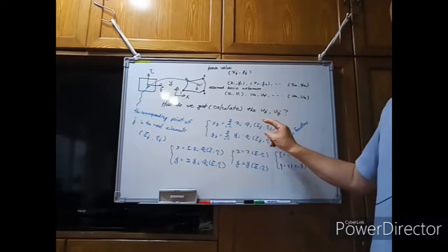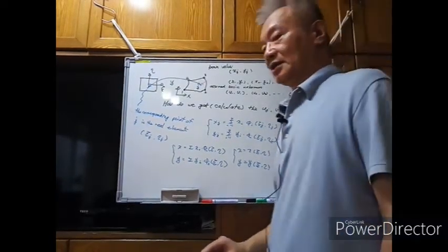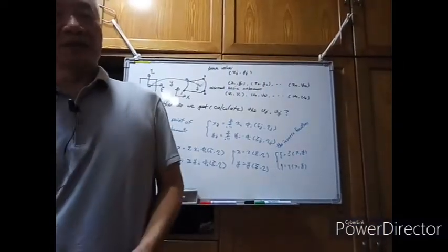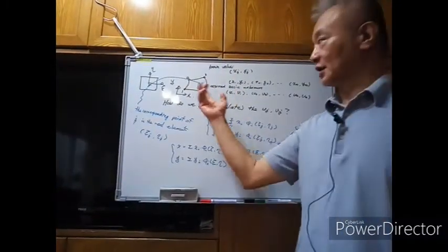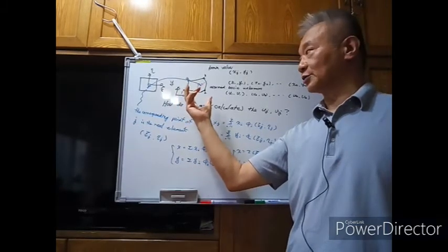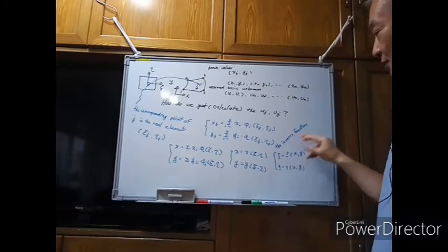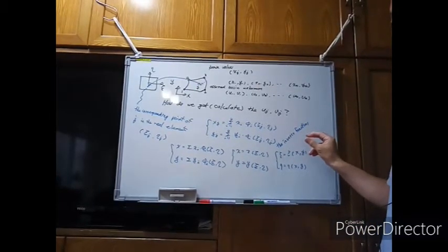Then you can find the xi j and the eta j. Okay, but if we got more nodal points, if we consider the element which uses 9 nodal points or 16 nodal points, then sometimes it is not so easy to find the inverse functions.